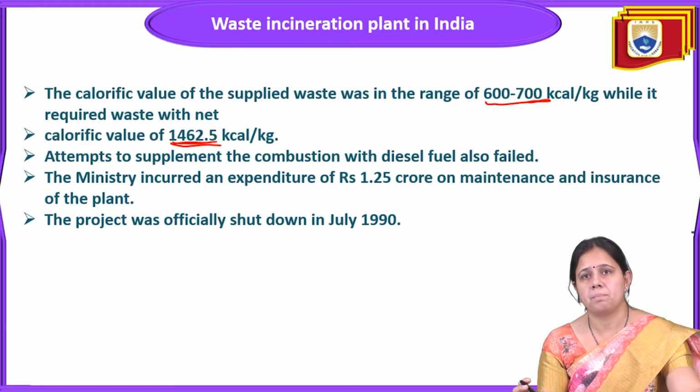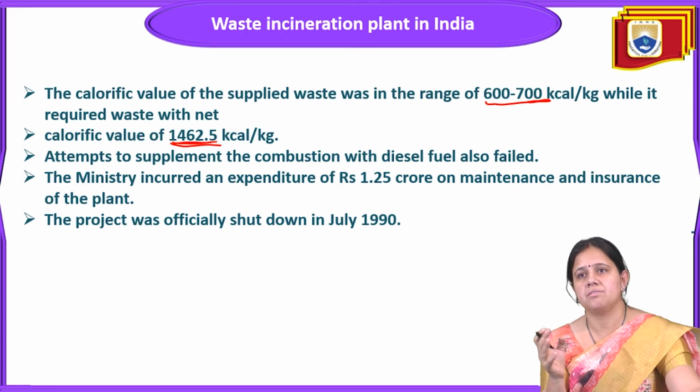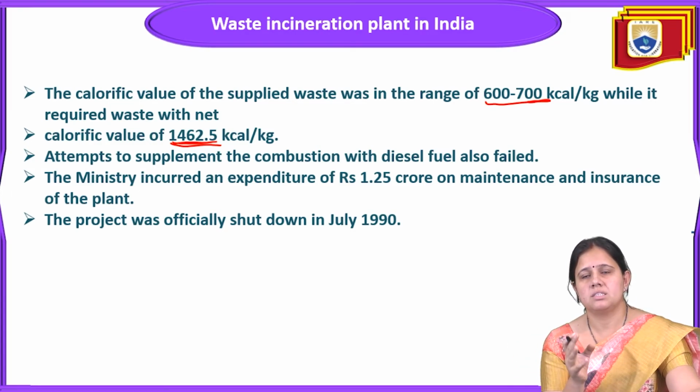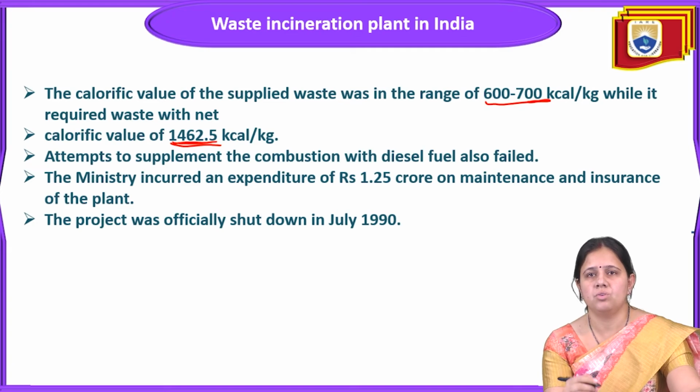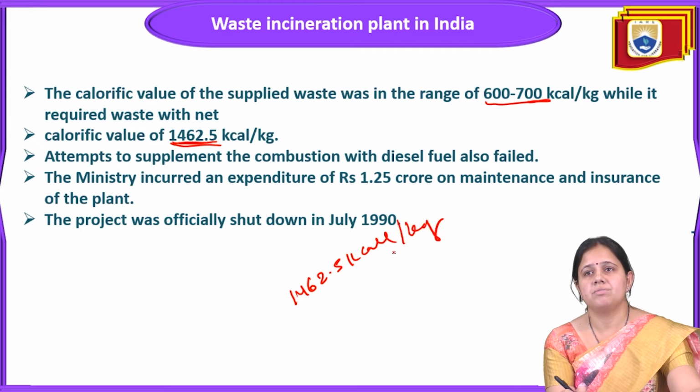An attempt to supplement the combustion with diesel fuel also failed. So the calorific value is important. This plant required fuel with a calorific value of 1462.5 kilocalorie per kg, but our waste has a calorific value in the range of 600 to 700 kilocalorie per kg.